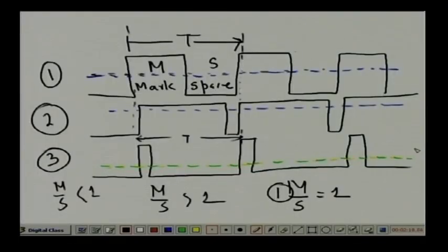I am modulating the width of the pulse, because the DC signal which I am getting is a very low value. So, we cannot transmit it; a DC signal cannot be transmitted, it is to be converted to an AC signal. That is the reason we are making it pulse width modulated. Once we get the pulse width modulation, we again take some DC signal here, and then we give it to a voltage controlled oscillator, right.